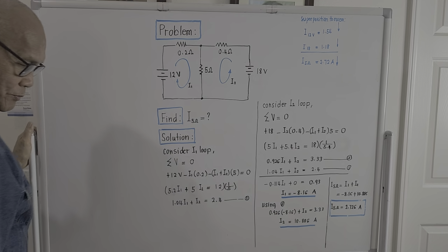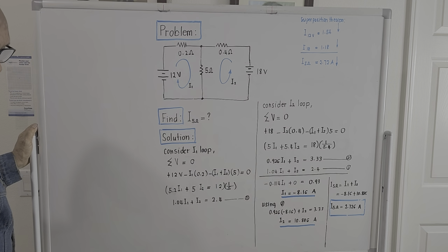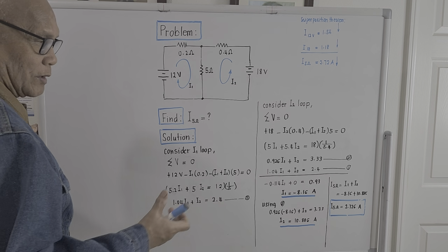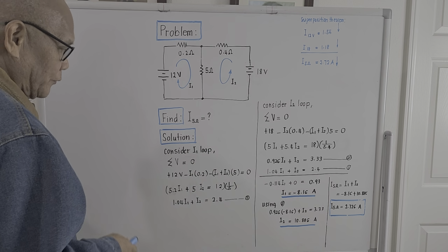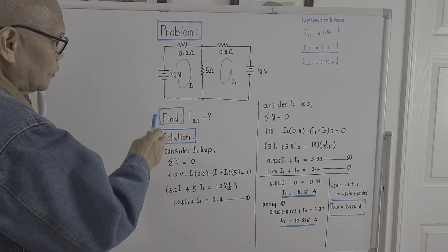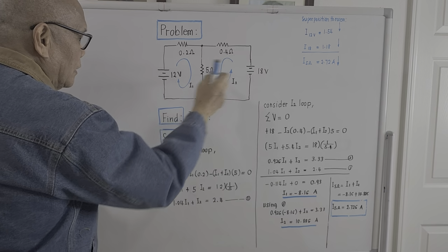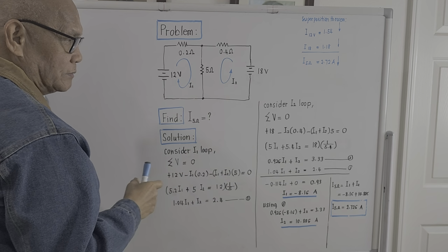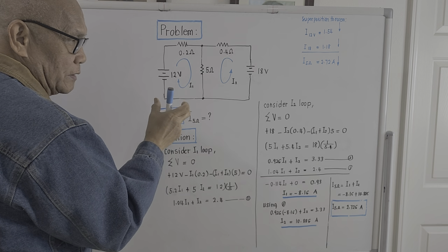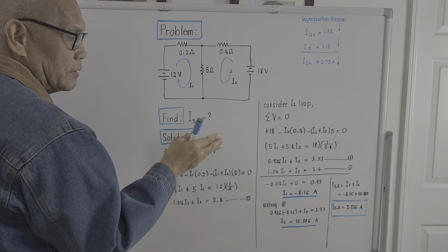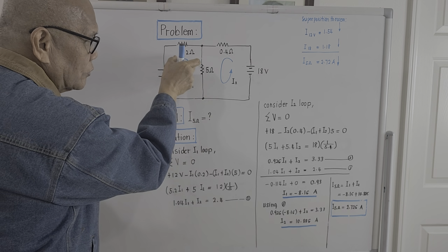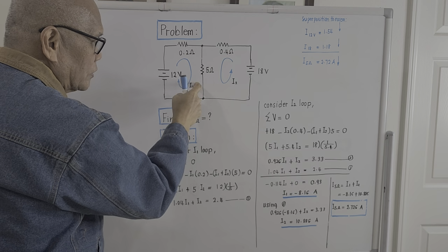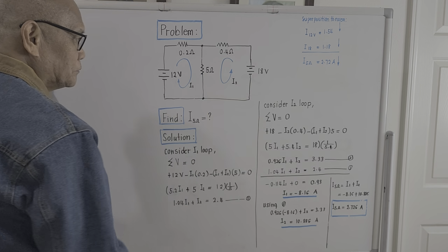The random topic for this morning will be a problem on direct current circuits, and this will be the circuit for this morning. We are given two voltage sources here. They are both batteries, so it's a direct current circuit. The resistances indicated on the circuit are 0.2 ohm, 0.4 ohm, and the load at the center has a value of 5 ohm.